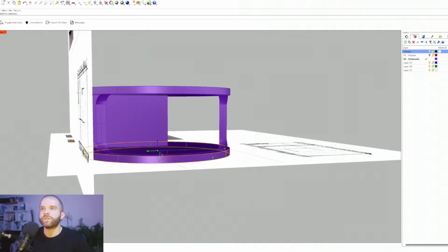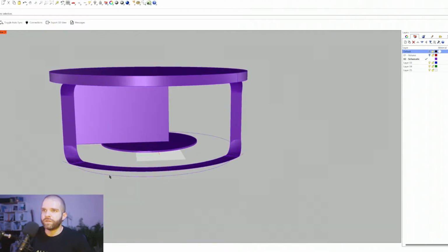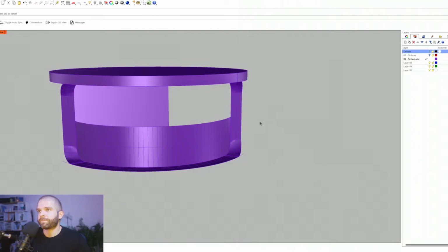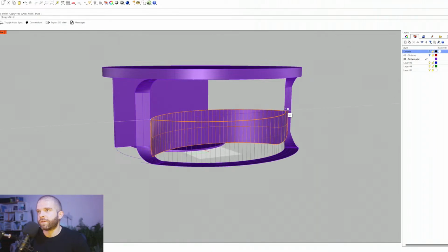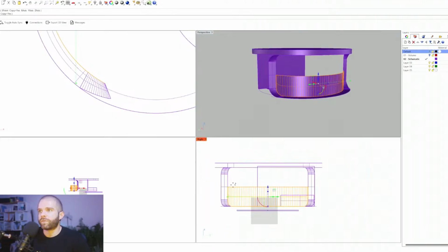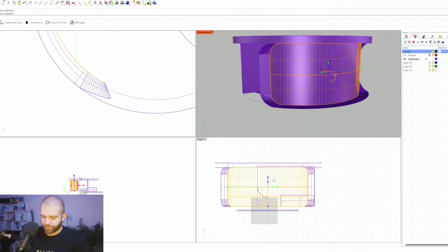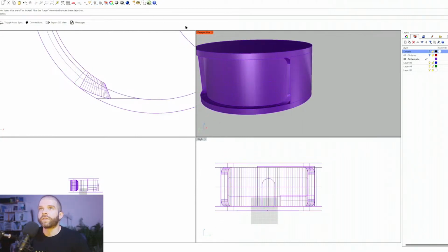Did it project? If we hide everything, it did project. So what I did there was I just projected it to the ground, so it'd be a flat curve like this, and I can put this to the middle point now, hoping I can loft these two together. Yes, and now I can mirror it to the top piece. Nope, mirror from the front view. There we go. Bam, and then join those two. All right, now my glass fits my ribbon. I can bring everything else back.